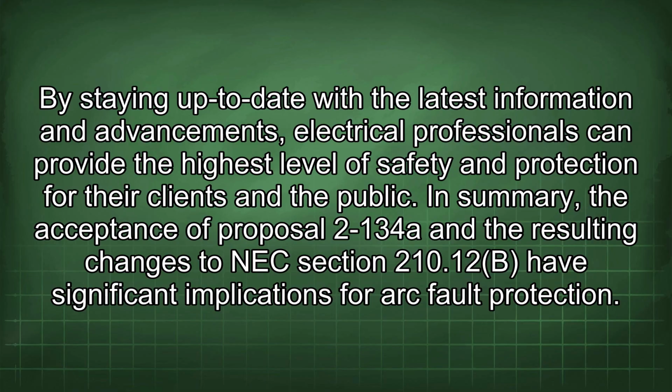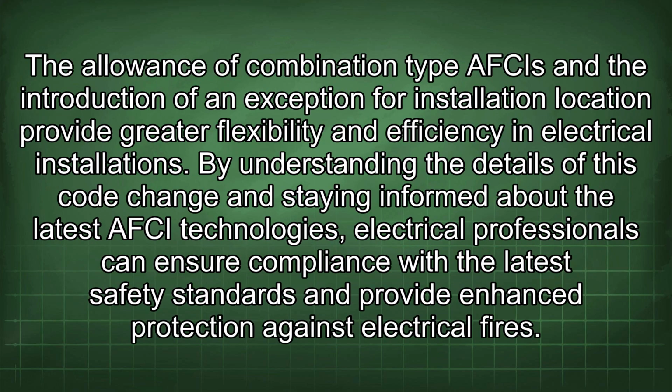In summary, the acceptance of Proposal 2-134 and the resulting changes to NEC Section 210.12b have significant implications for arc fault protection. The allowance of combination type AFCIs and the introduction of an exception for installation location provide greater flexibility and efficiency in electrical installations. By understanding the details of this code change and staying informed about the latest AFCI technologies, electrical professionals can ensure compliance with the latest safety standards and provide enhanced protection against electrical fires.